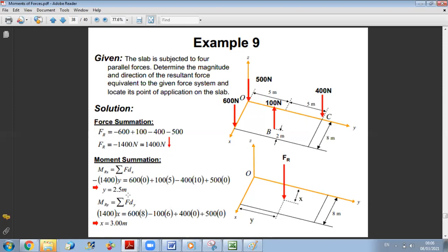The second step is I will reduce to moment about O. Now, here, in general, I said in 3D, it's easier to do the vectorial formulation. But here, no need for the vectorial formulation because look, the forces are very simple and they are all along Z. So what I can do, I can find the resultant moment along X and the resulting moment along Y. Since, as we said, no moment about Z because all forces are parallel to Z.